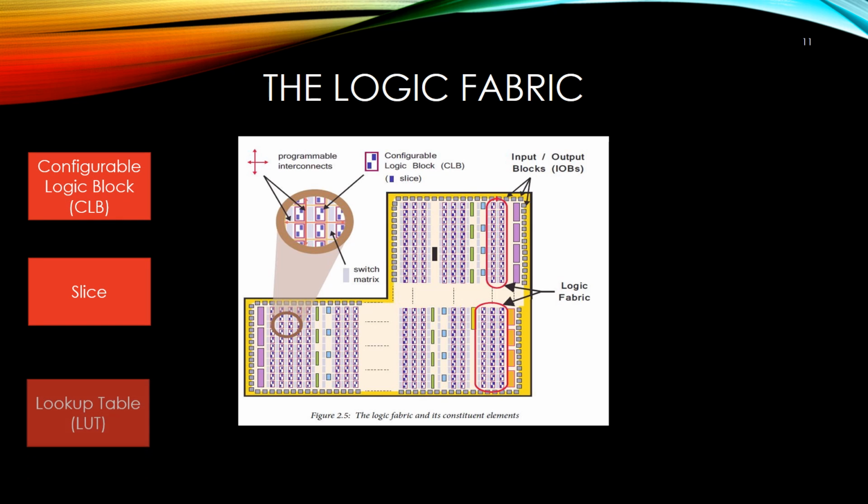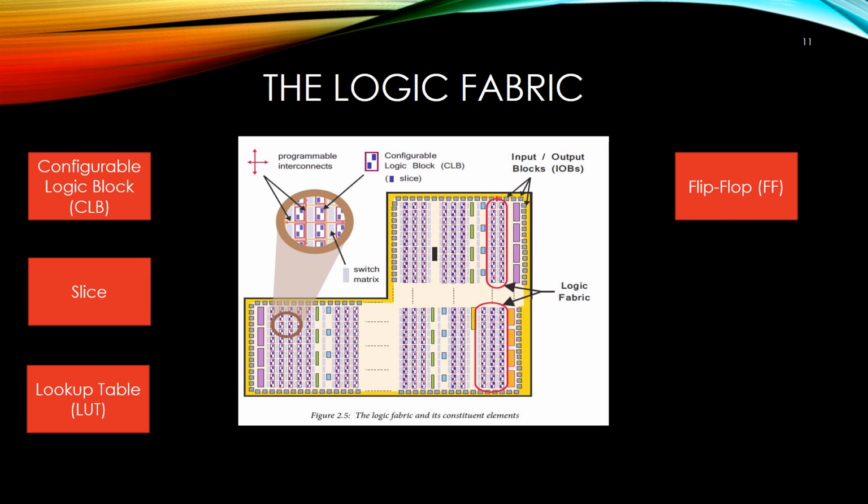The lookup table, LUT, is a flexible resource capable of implementing a logic function of up to 6 inputs, a small read-only memory, a small random access memory, or even a shift register. LUTs can be combined together to form larger logic functions, memories, or shift registers as required. The flip-flop is a sequential circuit element implementing a 1-bit register with reset functionality. One of the FFs can optionally be used to implement a latch.